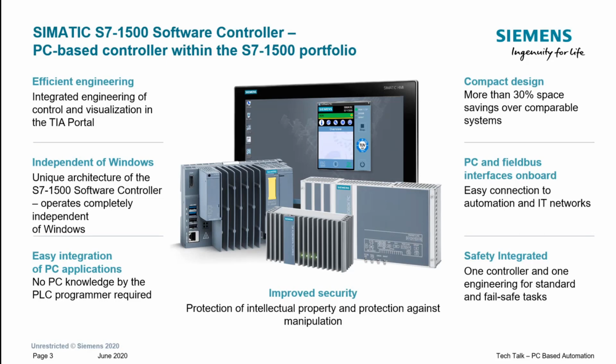But if we also want something that's a bit more in the form factor of a PLC, we have the device on the left of that graphic, the Open Controller, which you will have seen yesterday. Now, in terms of engineering these little devices, it's still the same look and feel. So exactly the same behavior as it would be in an S7-1500 full hardware controller. You engineer it inside TIA, you compile your code, and you download in exactly the same way.